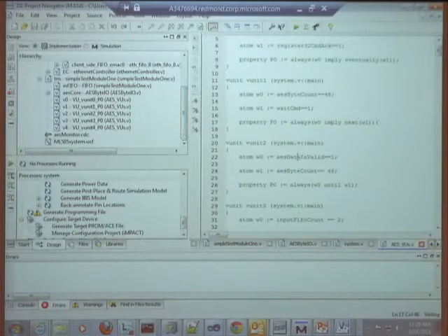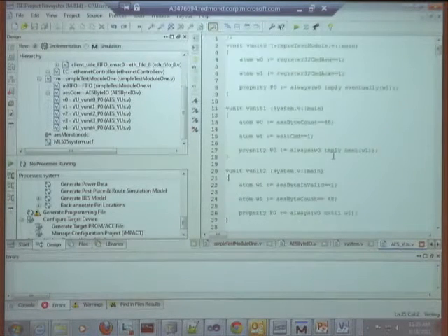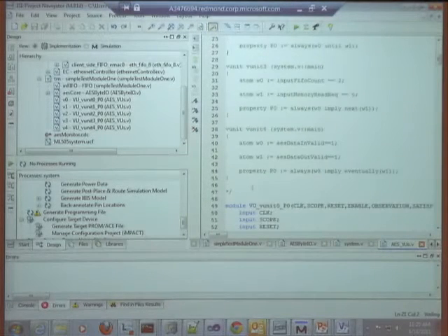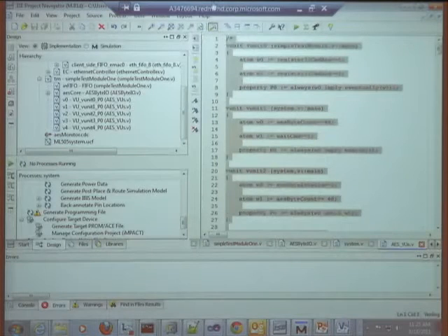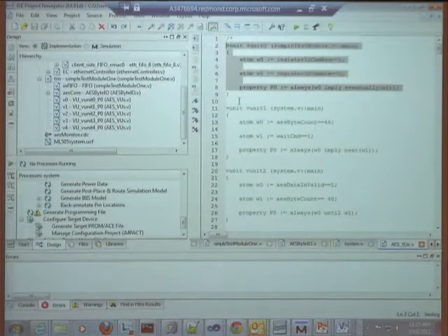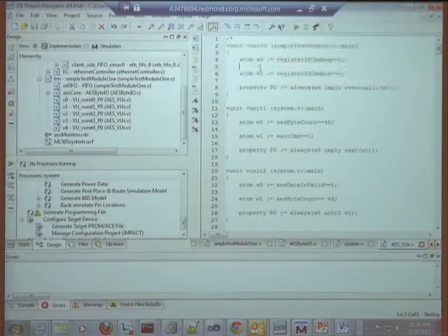So we are debugging an AS core, and I have these sets of assertions here written in the PSL language. This is an example of how you can write assertions in PSL. It starts with defining the atomic expressions. The atomic expressions evaluate to 0 or 1 at any time instant.